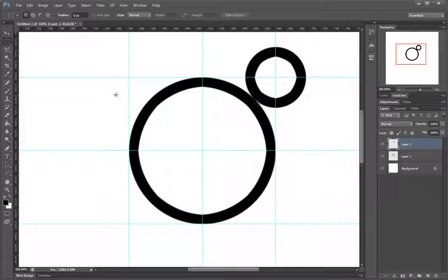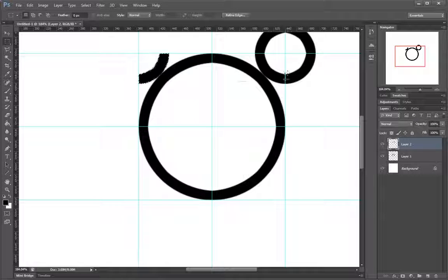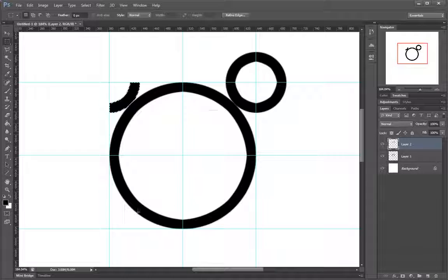It's obvious, right? I need this part because this one, the tile over here, is the tile in here, and this side should be this side. So I repeat that. I make a broad selection here, Control and Alt key to clone this. I can release any key from the keyboard now, and I've made my selection.